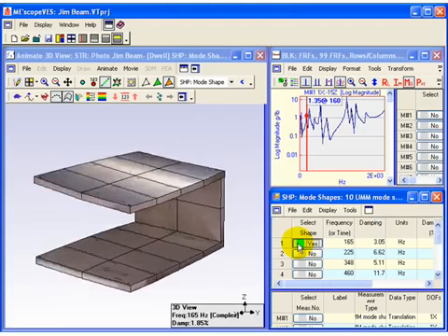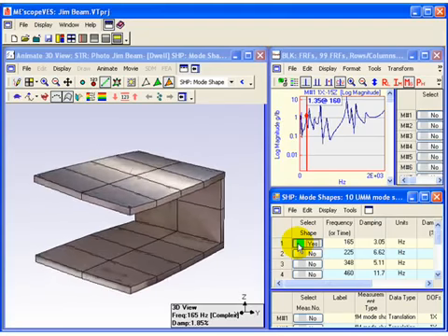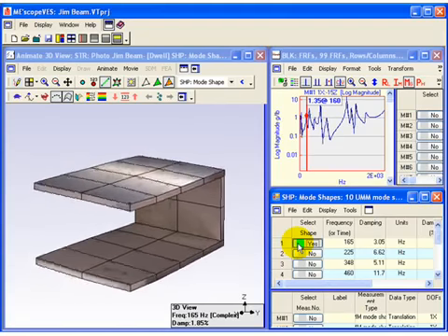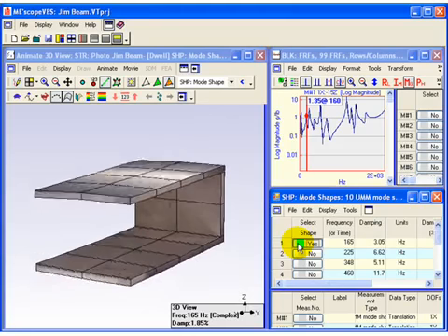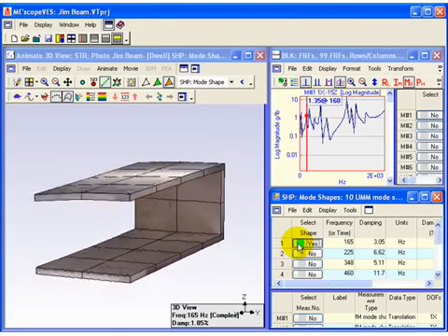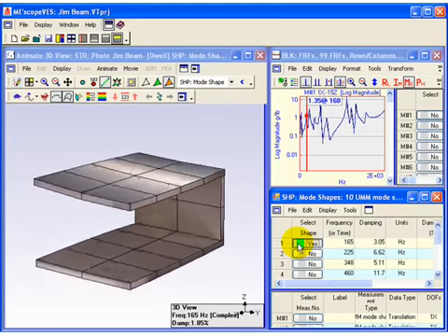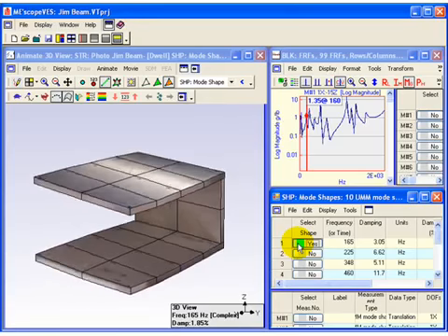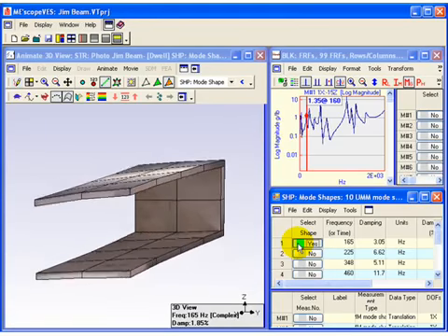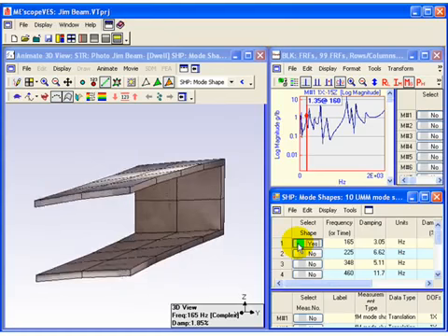Notice that this mode looks like a rigid body mode of the beam when only the Z direction is displayed. Of course, it would be very unusual for a mode at 165 Hz to have a mode shape like this. Nevertheless, if experimental data had only been acquired in the Z direction, this is the EMA mode shape that would be extracted from the data. Clearly, the dominant direction of motion of this mode must include either the X or Y direction. Had the X and Y directions not been measured in EMA, this lack of information in the mode shapes is called spatial aliasing.